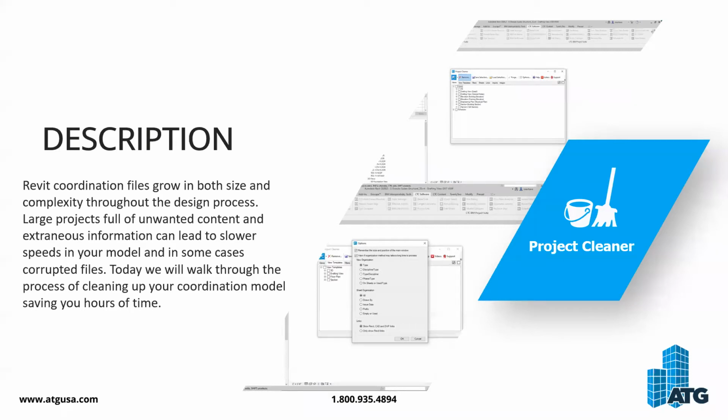And we're going to fix the issue of having slower models because of unnecessary content, from what we have in our own model, right? We all have those maybe 1 through 100 section views that we use to design in our model, and we don't realize the impact they're taking and the additional size they add to our models. Or maybe it's a rendering, right? We keep our rendering in our project rather than linking it in. How do we know if it's in our project or it's linked in? You can find it easily with the Project Cleaner.